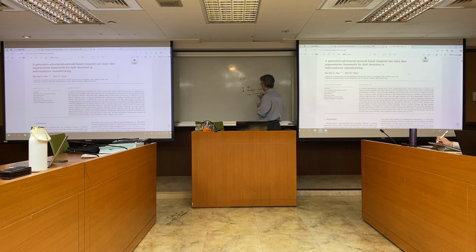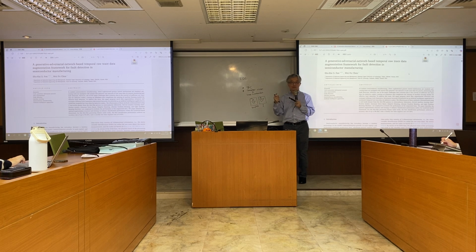Subtraction. Yeah, this is pixel to pixel. This is what we call the template. So this instance is under inspection. This minus this: if they are identical, 3 minus 3 is 0. In the 8-bit representation, 0 represents all black.